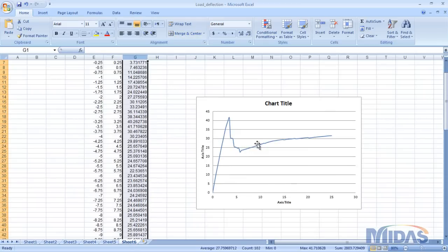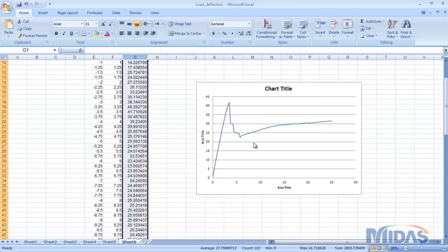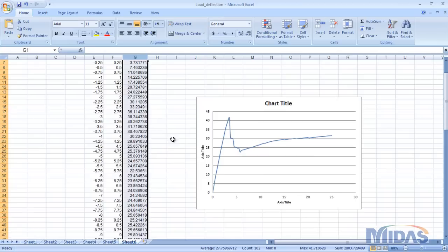So I think when we wish to simulate the crack propagation or the cracking within concrete or any other material, or if it's a masonry structure, displacement control loading is much more recommended to get more reliable results.